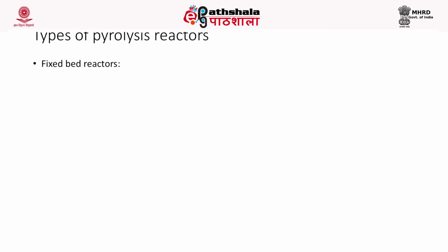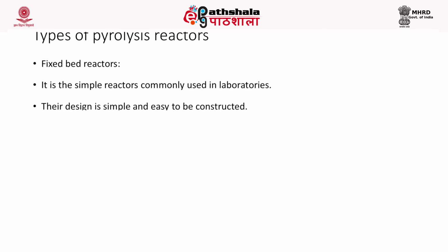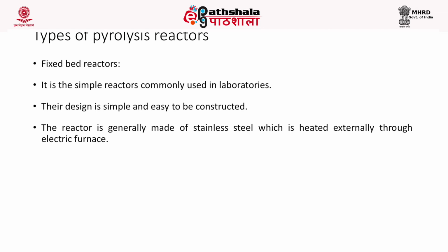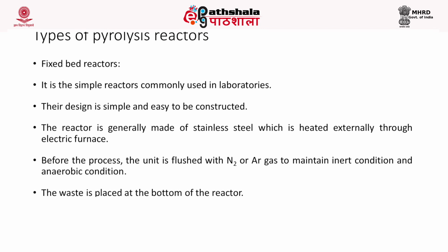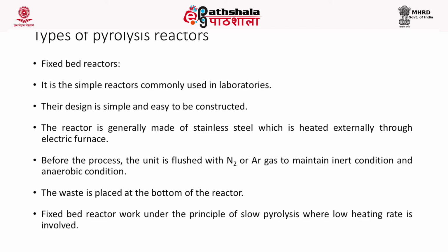Now, we'll discuss the pyrolysis reactors. Fixed bed reactors are simple reactors which are commonly used in laboratories for the pyrolysis process. They are simply designed and easy to construct. The reactor is generally made of stainless steel which is heated externally through an electric furnace.